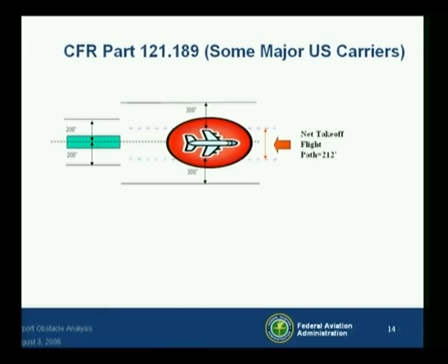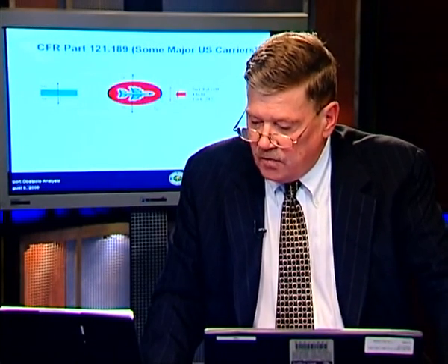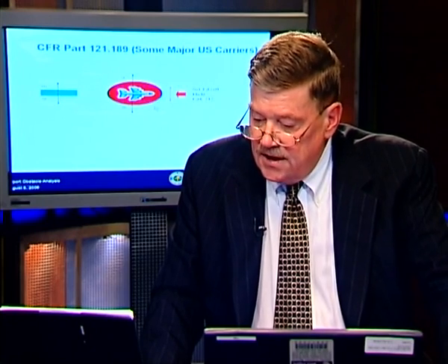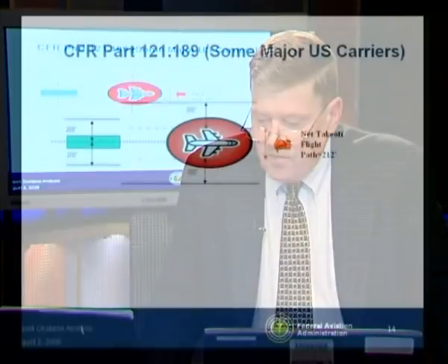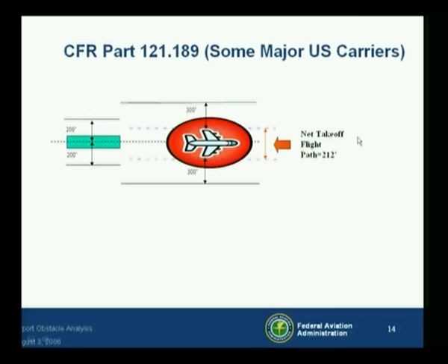So the flight standards interpretation of this, to make this a realistic rule and useful for us, is that the interpretation of policy from our end is that the net takeoff flight path includes the wingspan of the airplane. So a Boeing 747 with, say, a 212-foot wingspan would have to clear obstacles after the airport boundaries by a minimum of 300 feet laterally on each end of the wingtip. The new A380, I believe, has about a 276-foot wingspan, so that will require 300-foot obstacle clearance on the individual wingtip. Of course, a DC-9 or a 737 will have a smaller net takeoff flight path.